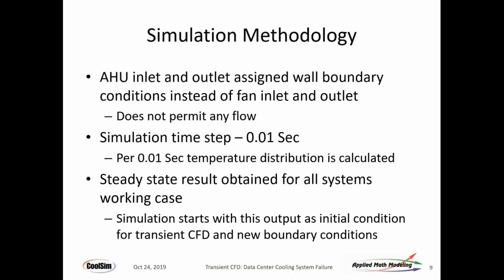So the methodology is to, from a simulation point of view, assign the inlet and outlet for those air handlers as sealed, no flow exists. We pick the time step. This is important. It's a transient simulation, you have to pick a time step. And effectively, transient simulation is steady state solutions at each step. So at each time step, we solve a complete steady state solution.